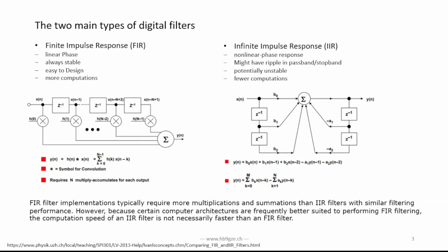All right, the two main filters we see all the time are, as we mentioned already, this FIR and this IIR. And really the name of the filter says it all. FIR means finite impulse response. If you have an input signal, let's say 1 volt, and you drop it to 0, and then you monitor, the output will eventually be 0. If you do this with the infinite impulse response filter, the output will never ever get really to 0, theoretically.